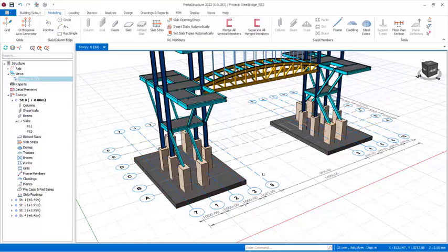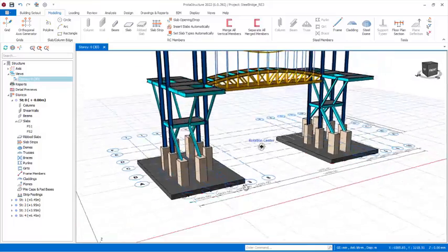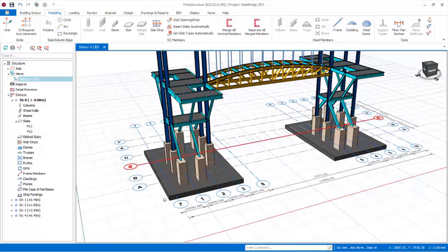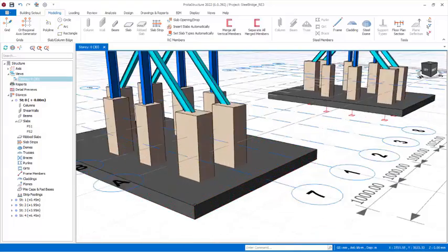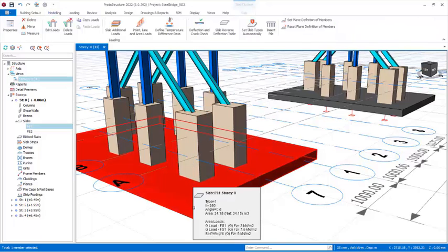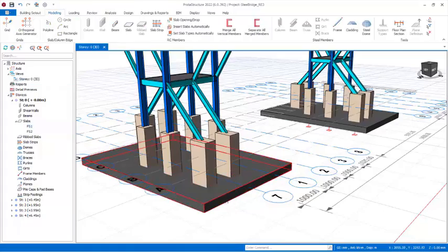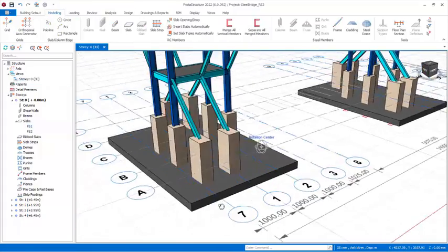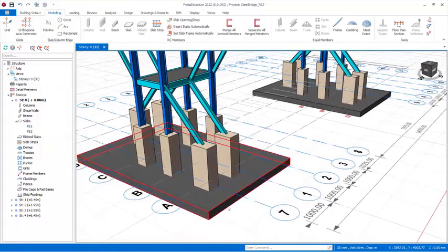This design is enough. Okay, except if there is any punching. If you are experiencing any punching, you can apply additional footings under these columns, or you can as well increase the thickness of the floating raft so as to cater for the punching successfully.